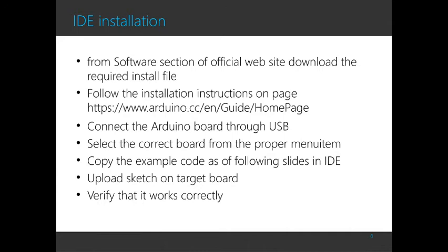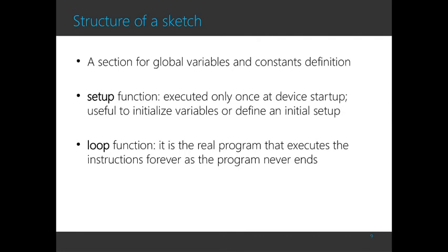So you can also try and copy an example that I reported on the following slides to make it easier for you to try your board, and you press upload to upload the sketch on the target board. Then the board starts working.